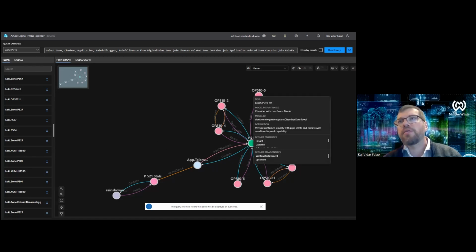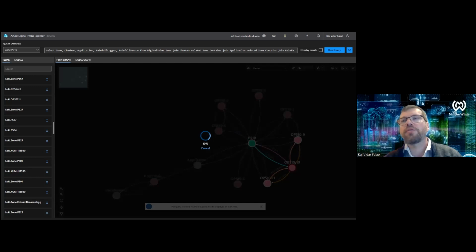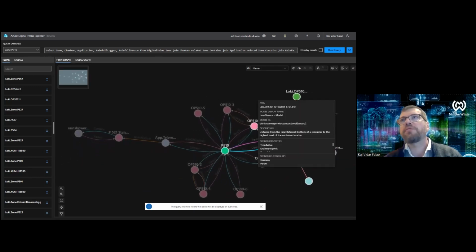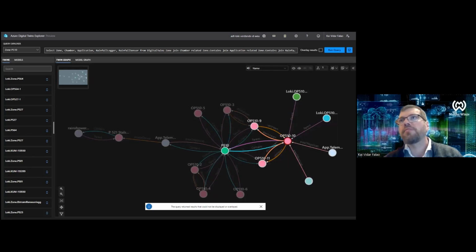If we go in and have a closer look at this chamber, for instance, we see that we can also have both the level and maybe even the temperature monitored for these chambers. To monitor this, we actually use IoT sensors in addition to the ordinary process automation equipment. So this is not PLC based, but IoT sensor based information that we collect.